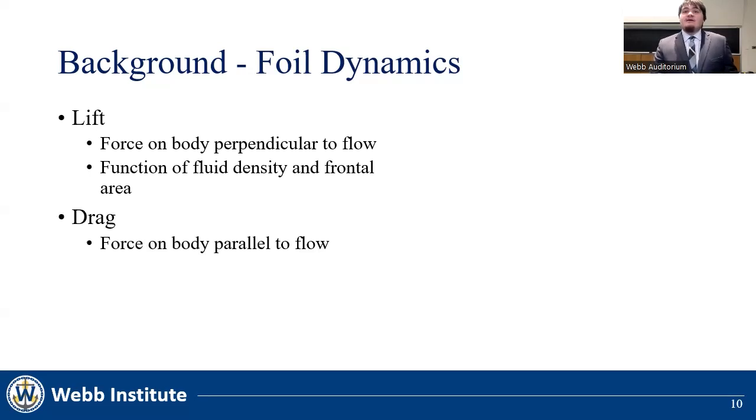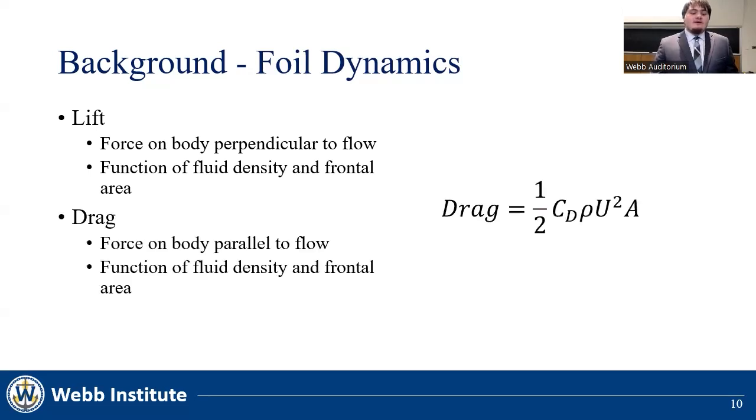Drag is the force on the body parallel to the direction of flow. It is also a function of density and frontal area, and it is given by the equation above, where CD is the drag coefficient, and rho, u, and A are the same values as in the lift equation.